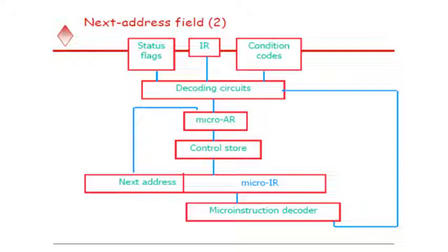The increase in branch microinstructions stems partly from limitations in assigning successive addresses to all microinstructions that are generally executed in consecutive order. This problem prompts us to re-evaluate the sequencing technique built around an incrementable microprogram counter.